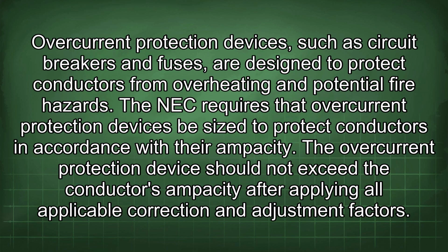Overcurrent protection devices, such as circuit breakers and fuses, are designed to protect conductors from overheating and potential fire hazards. The NEC requires that overcurrent protection devices be sized to protect conductors in accordance with their ampacity. The overcurrent protection device should not exceed the conductor's ampacity after applying all applicable correction and adjustment factors.